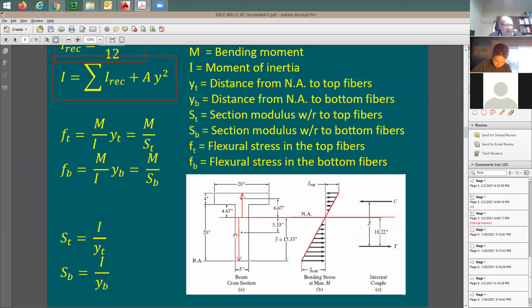In a T-section like this, first you need to find the centroid. And the neutral axis is going to be right at the centroid. This is great, so it's going to be simple. The neutral axis location you can figure out based on the section properties in terms of dimensions, not on the concrete strength. Concrete strength is a completely different issue. But the neutral axis location is going to be based on this width, this thickness, and this depth, if you like, and this thickness.